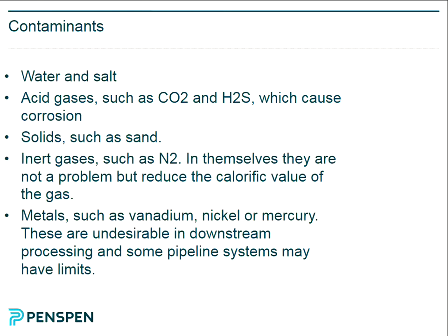This one here is a gas condensate. This dotted one here is a volatile oil, and this dotted one here is a black oil. You will see that the shape of the hydrocarbon phase envelope changes depending on the composition. So it goes further to the right. You see this little thing with C? I'll explain what it is in a minute. It moves to the right, so the shape changes. Plotting this out and knowing where you are on it for a hydrocarbon is very important.